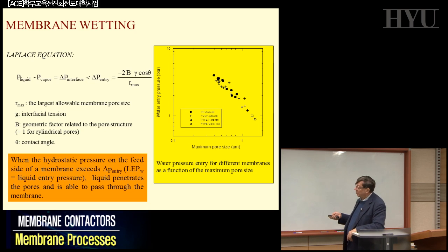That is the parameter, this L, what we call liquid penetration pressure. For any material with a certain level of hydrophobic character, the possibility that the liquid penetrates or not is related for sure to the contact angle, that is the theta here, but is also related, you see in the denominator, to the size of the pore.